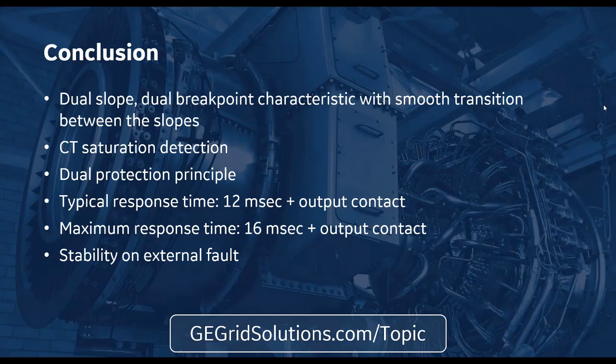That's been done for a long time because, like when we talked about pilot wire relays, HCB relays back when we first were starting to use line differential, the CTs were paralleled. And when we upgraded them to microprocessor relays, because we didn't want to mess with the circuit, we still have them paralleled. But as I said, I've seen a lot of misoperation because of that. But those are mostly when you have sources on both CTs. If you don't have sources on both of those CTs, and only one of them is going to be subject to fault current, then you might be okay with paralleling the CTs.